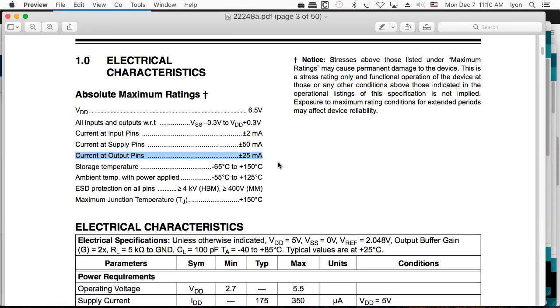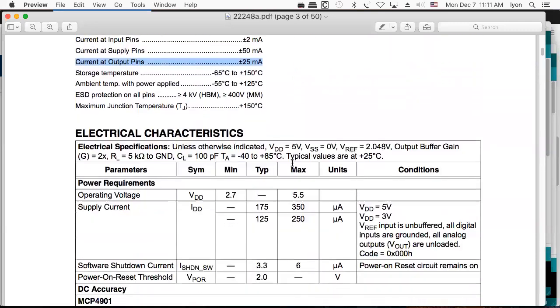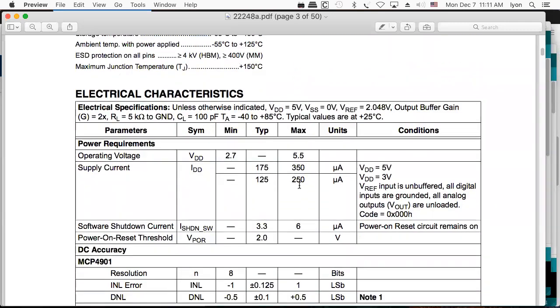And so that's why I say, look, you've got to have amplified speakers or a very low power crystal earphone, or iPod headphones, or something that's not going to draw a lot of power, because this thing does not have a lot of power for you to draw upon. And you can tell that right away because of the data sheet, right? He just doesn't have it. In fact, if you look at current draw, it's measured in microamps.